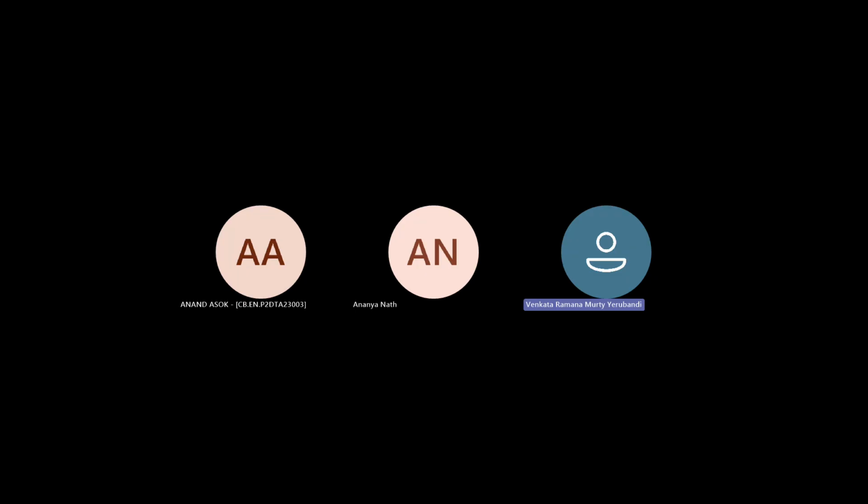So that kind of thing will be there like an algorithm, because every edge is common for two triangular facets. That kind of verification is to be done, whether the edge is common for two facets. If it is not common, then there is an error. We have to verify the entire STL model that is made out of triangular facets, and then repair it. So that process is there for STL repair.